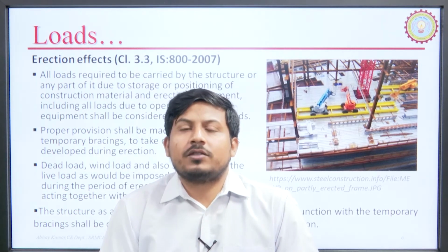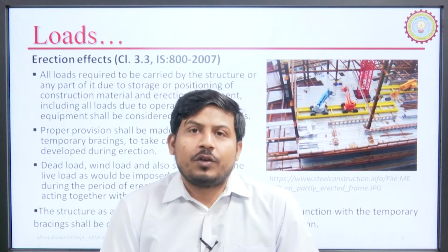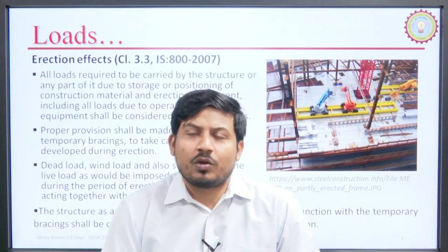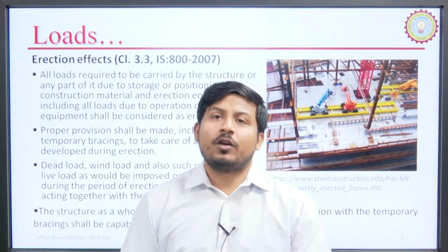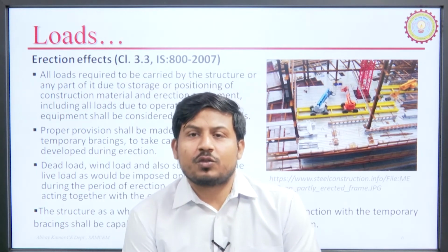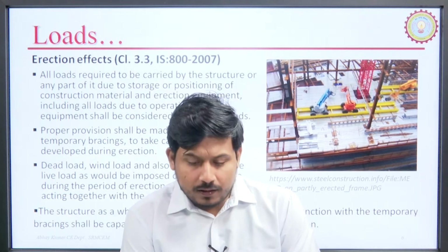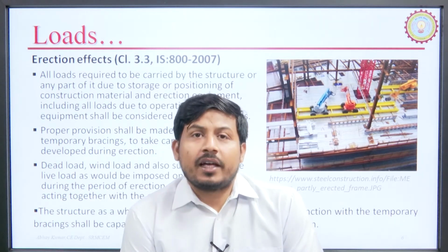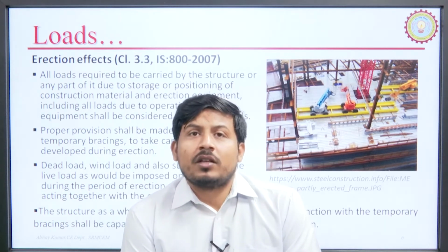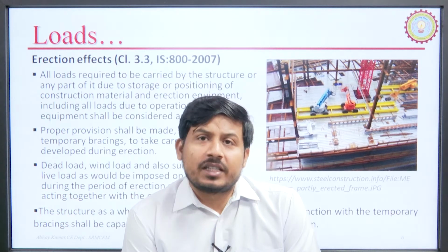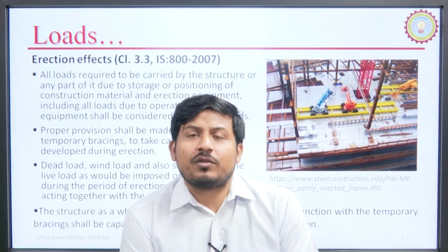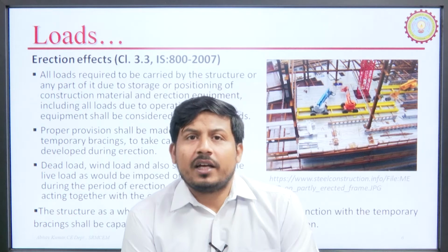When we design, we go for the dead load and the imposed or live load coming on the structure, but during construction there is also load coming because of the storage of construction material, cranes and other erecting equipment. The load coming because of the storage and the occupancy of those materials comes under the erection effect.